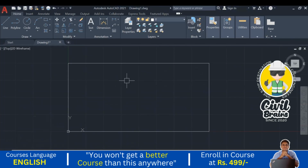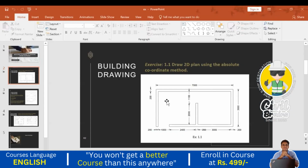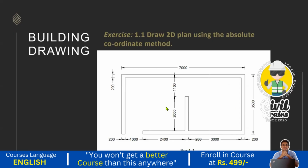So the first method we are going to use is the absolute coordinate method. In the absolute coordinate method we need to find out the coordinates, the x coordinate and the y coordinate. So how to find that out? That is very easy. We need to find how far to go in the x direction and in the y direction. So we find it point by point.